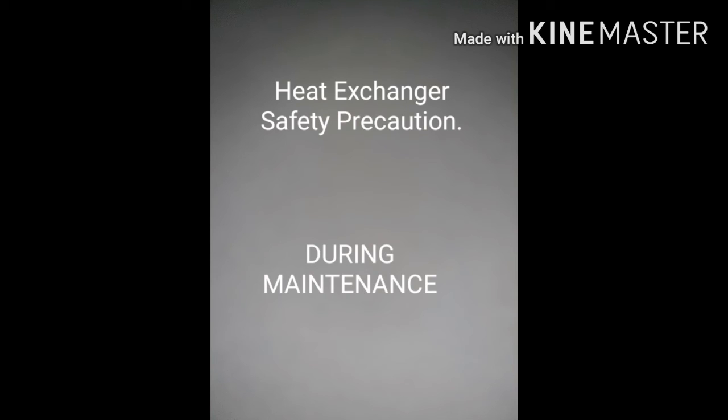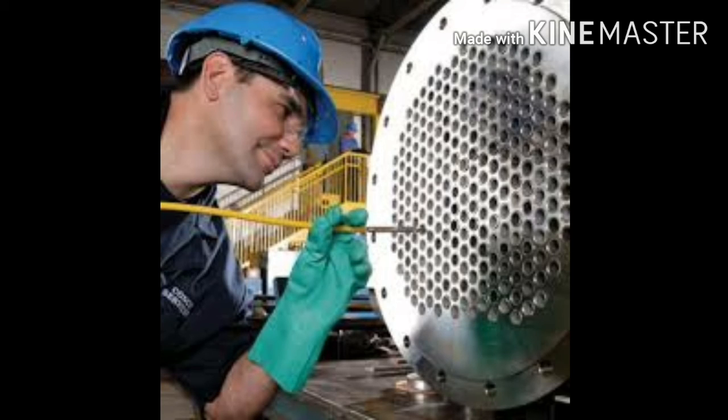The final one is the heat exchanger safety precaution during maintenance. Number 1. Follow LOTO or the lockout tagout procedure when you maintain the heat exchanger. Make sure all inlet valves are already secured and tagged appropriately.